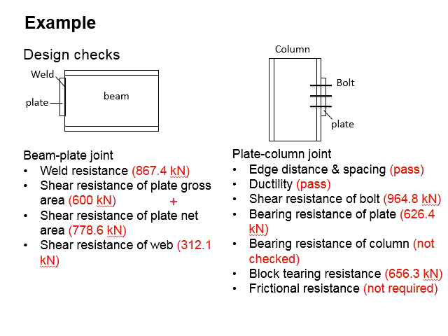With that, you will expect the connections fell between the plate and the beam, which occurs at the shear resistance of the web. That means ultimately the failure is within the web of the beam, where the plate and the weld will tear parts of the web off, leaving the rest of the web together with the beams on the other side.